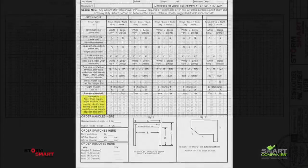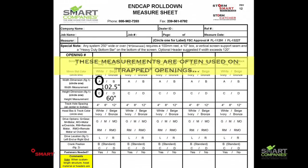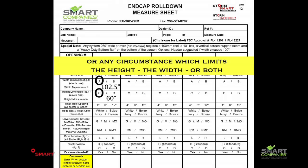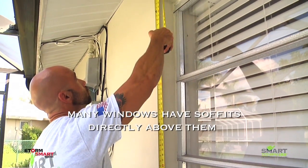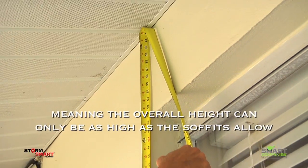The A and C measurements are the overall outside to outside width and height measurements. You would often use these dimensions if the opening is trapped, meaning your width and height are predetermined because you have to attach to the inside of the opening or some type of circumstance which is limiting the height, the width, or both. For instance, many windows have soffits directly above them, which means the overall height measurement can only be as high as the soffit allows.